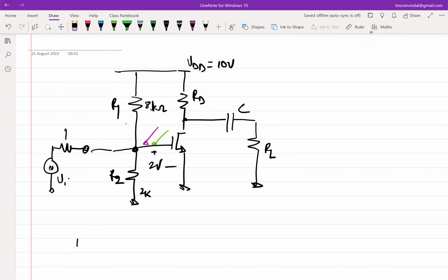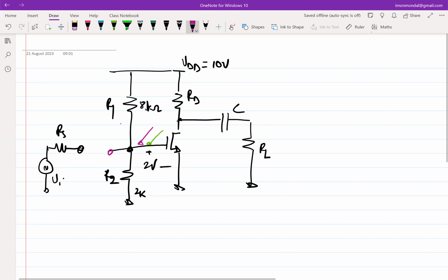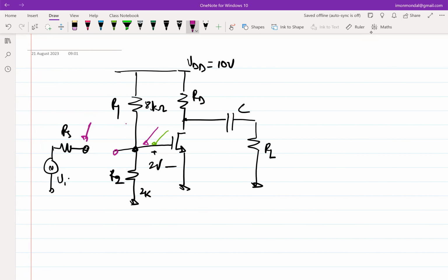One of you said capacitor. Yes, capacitor is a solution, obviously. But if I have to build from scratch, what is the root cause? The root cause is the fact that, before I connect these two, the DC voltage on this node is what? What is the DC voltage at this node? VI is not DC. VI is the incremental input. No. This node, 0, right? The DC voltage here is 0. What is the DC voltage here? 2 volt. So naturally, if I connect them directly, current will flow and it will load.